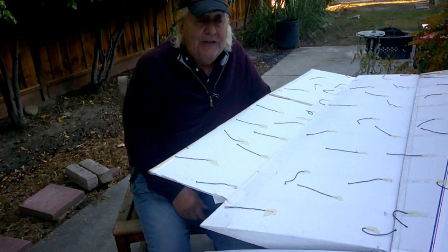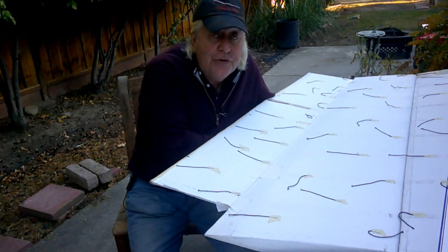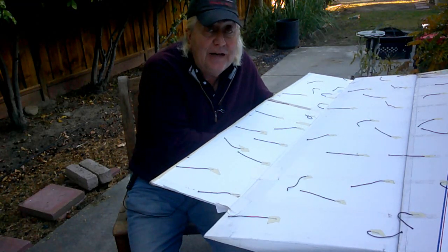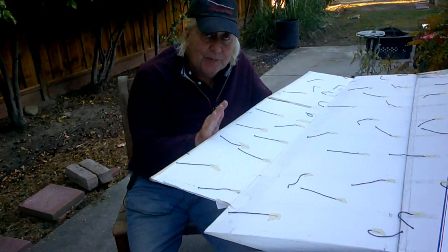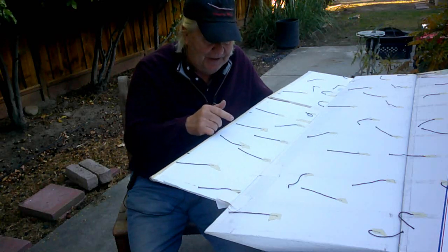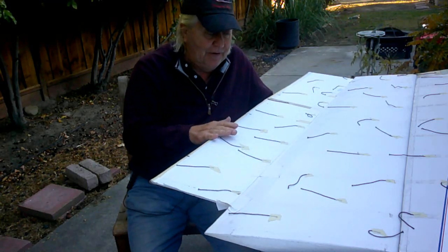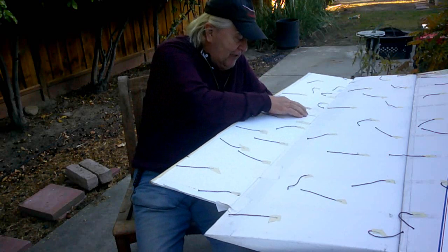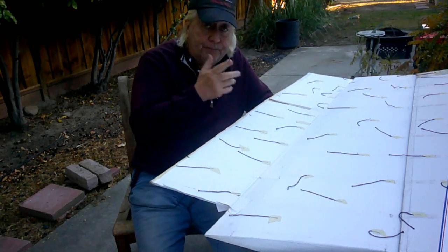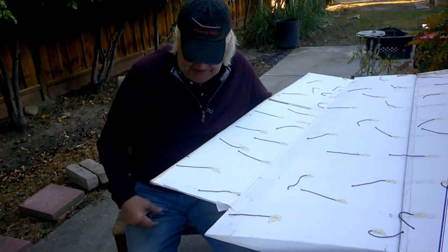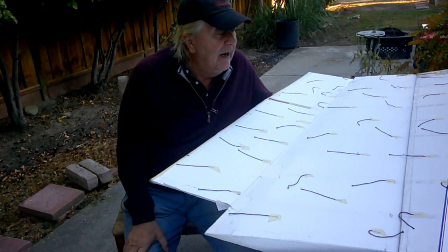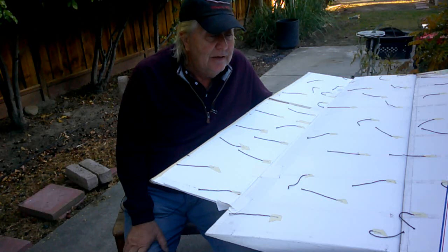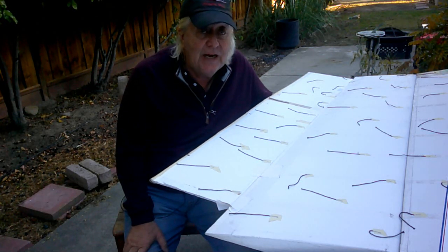And welcome back. So there's no sound on that, and unfortunately you can't hear me calling out the deflection angles of the elevon, but the maximum down deflection, as I mentioned in the video, I hope I mentioned it, is about 25 degrees. And the flow is staying attached up to about 20 degrees. Some cases 22, 21, depending on what the velocity of the wind was. And it works like gangbusters. Now I can get a lot of deflection, the flow stays attached.